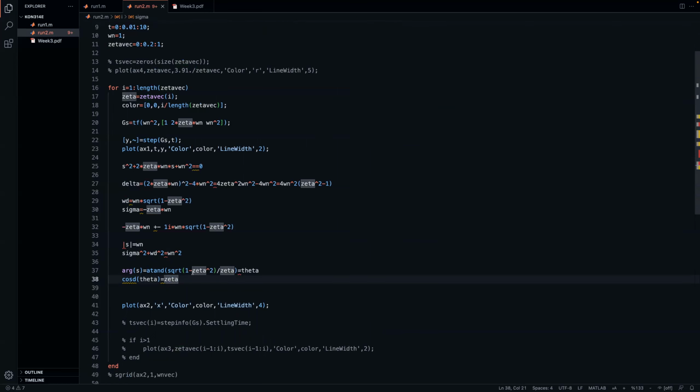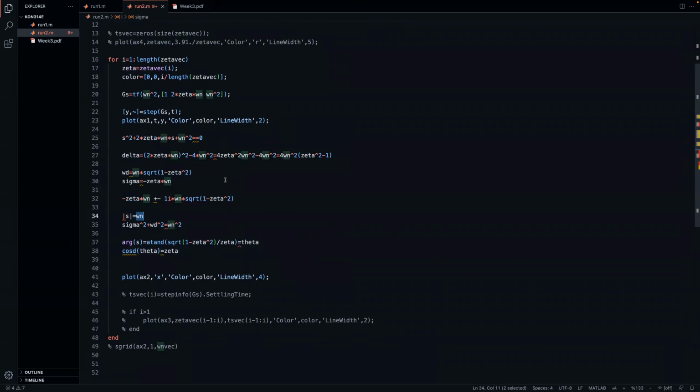And if you think about it, when we fix omega n, you get a circle at the origin with a radius omega n. And if we fix zeta, we fix theta to a certain angle, and that's actually a line on the s domain. So that's the reason why in a moment we will see that zeta is going to form some lines and omega n is going to form some circles, and their intersection is going to define our pole pair. So that's important to know.